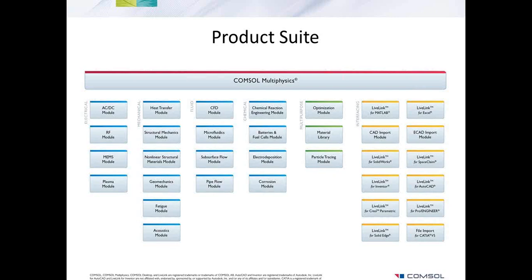In this way, you set up the physics, the mesh, and the material properties only once, and you simply run your model and use the parametric sweep to solve it for multiple cases. It's basically like putting a for loop around your entire model, and then finally you can look at the plots in the post-processing. You can find out how the response changes as you change the parameters.